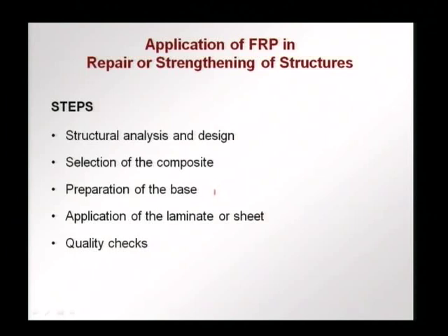We are going to adhere, we are going to stick the FRP onto a concrete surface. We know that the FRP is very strong, very stiff, and if the base is weak, the base will fail instead of the FRP failing or even reaching stresses close to failure. So the preparation of the base is very, very important. We cannot use FRP on a base or surface that is very weak, dirty, or not well prepared.